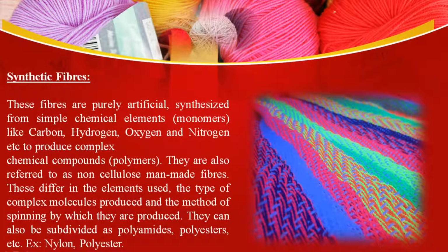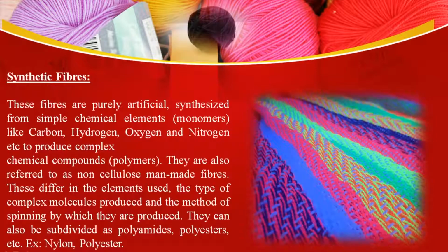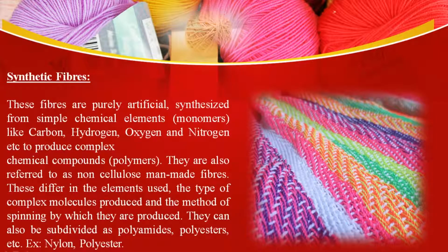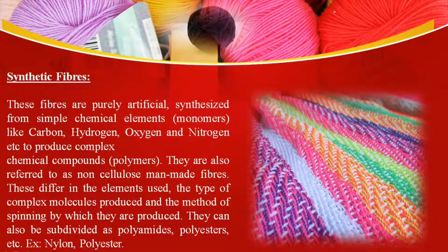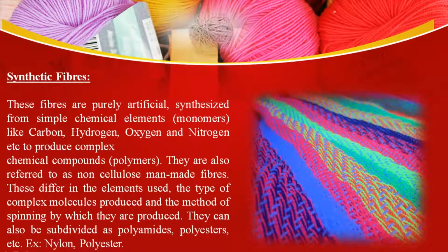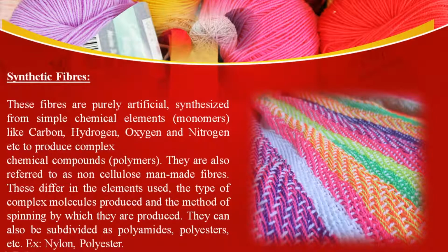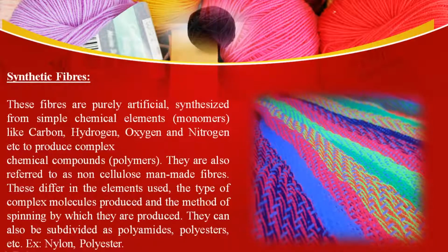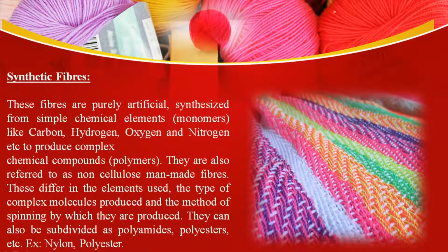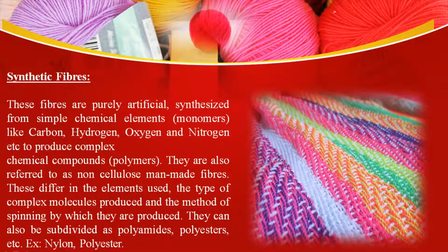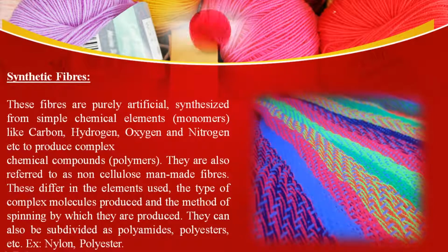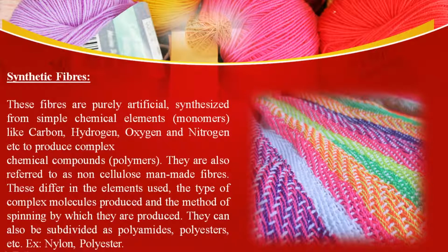Coming to synthetic fibers, these fibers are purely artificial, synthesized from simple chemical elements, monomers, like carbon, hydrogen, oxygen and nitrogen etc. to produce complex chemical compounds, polymers. They are also referred to as non-cellulose man-made fibers. These differ in the elements used, the type of complex molecules produced and the method of spinning by which they are produced. They can also be subdivided as polyamides, polyesters, etc., for example nylon and polyester.